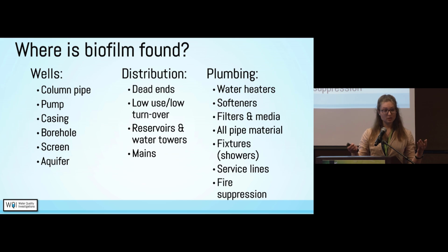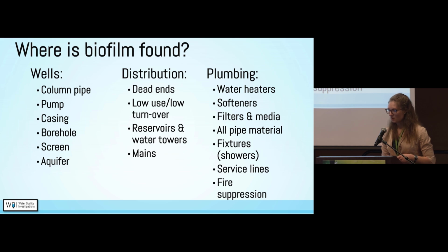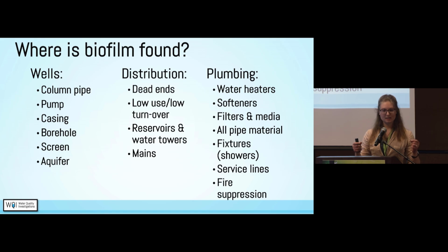Those usually are not booked regularly, and so the shower fixtures basically sit and they're not drained. They have water sitting in them, and that can be a huge factor for Legionella. We see a lot of growth in service lines. I'm going to touch on that a little bit later. And then fire suppression systems are also a huge area for growth because water is just sitting stagnant in those pipes constantly.